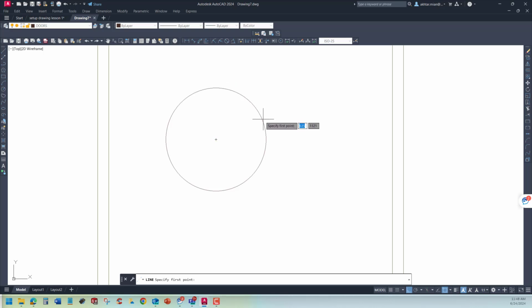As soon as you go to the circumference, the center point snap is on. So it will click over here, enter, again go to the line, pick the center and draw the line like this. Okay. I know I'm going a little bit faster, but you can stop and pause and go back. This is the benefit of the video. So let us trim this now. Trim.